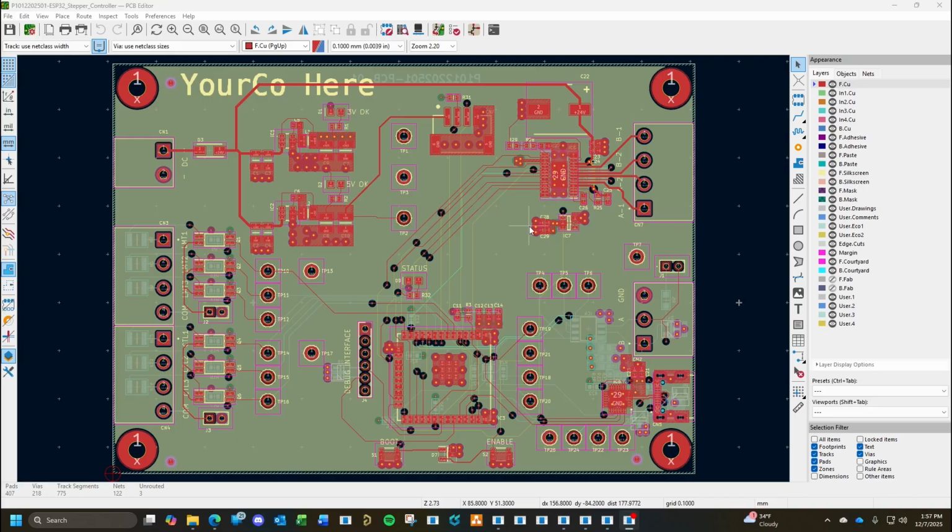So now we're going to go through, review, make sure we don't need to make any changes or adjustments, and update our design rules. We try to get a zero error design rule check. It's going to be limited to the different options we can set in the DRC checks, mainly spacing between traces and pads, hole sizes, things like that, text sizes. So we'll see about fixing all that.